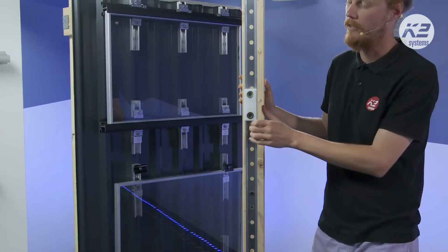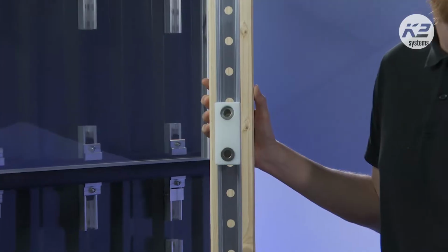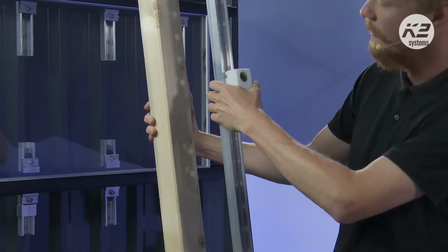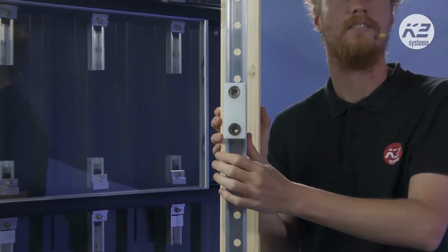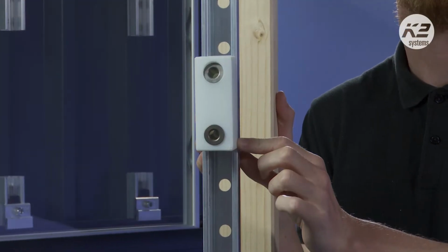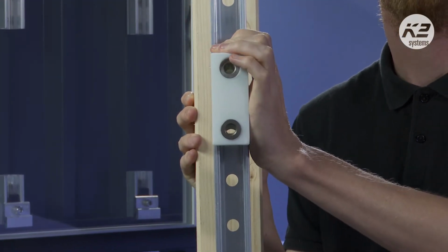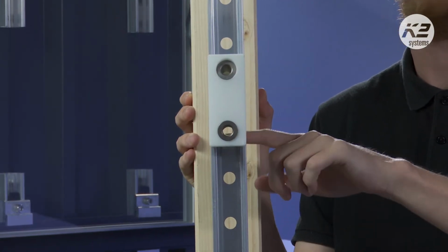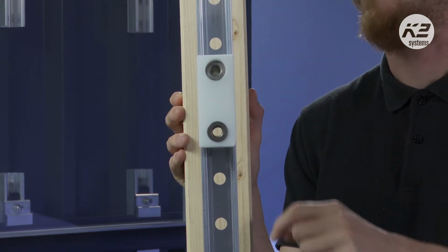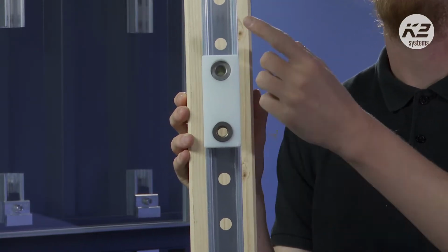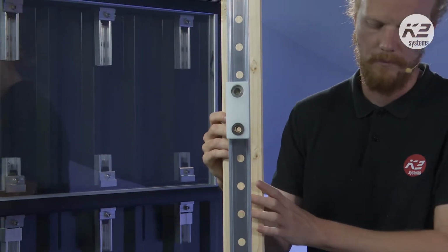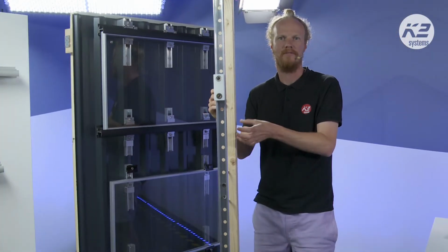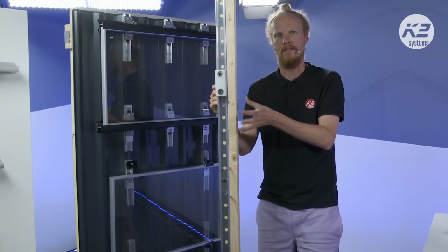And then you can put the little jig on top and align that. Maybe I can align it a little better so we can see. If we align that perfectly with the hole that's in the rail, I'm a little bit off as well, but you get the idea that now this hole is going to go straight through. This will be a straight one. And on top, you're going to have to move it up or down a little bit to get the 15 degrees that's required for either the top or the bottom. So this is the fixing that's required for the specific type of facade that you might have.